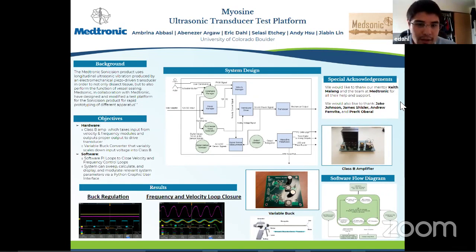Our project was transforming a pure sinusoidal wave, which only has components at the resonant frequency. So we didn't really need to use a chip that would compute the entire transformation. Rather, we could evaluate the transformation at the resonant frequency, and that would be enough.